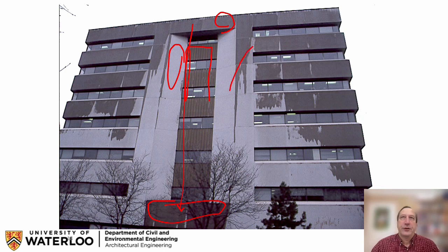Important other features you can tell from the staining is that there's rundown going on. So the concrete at the top here is getting quite wet, and therefore it's saturated and it begins to run down. The windows, of course, don't get saturated. They don't absorb any water at all, and so the water will run off.